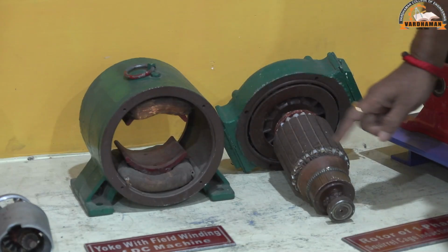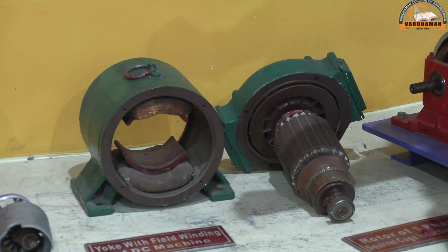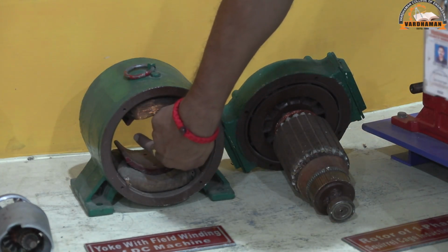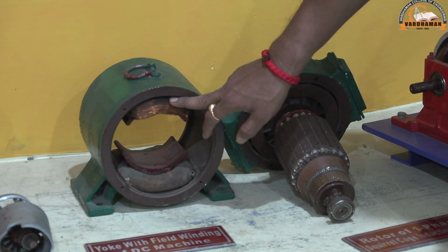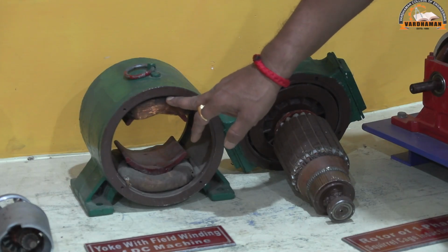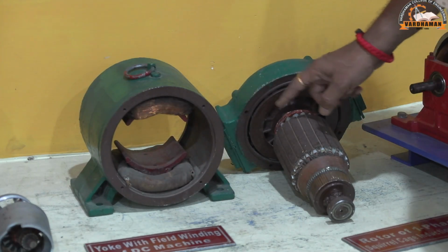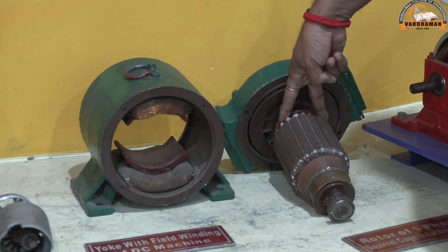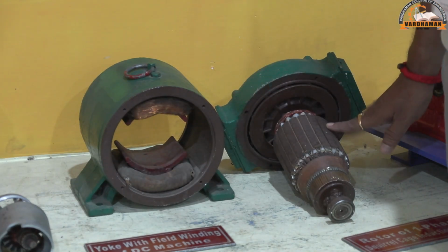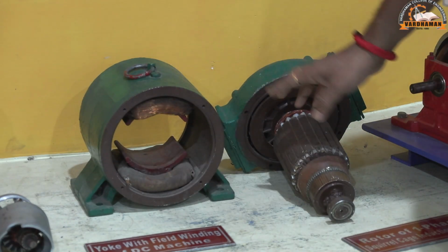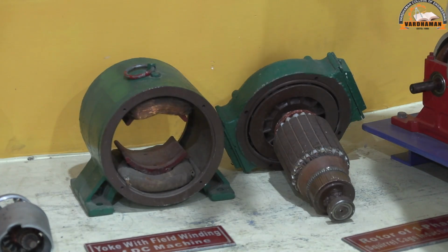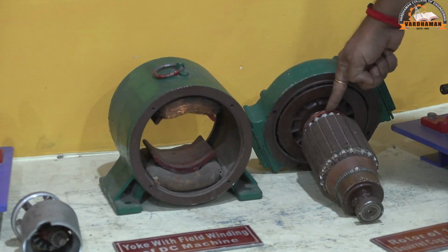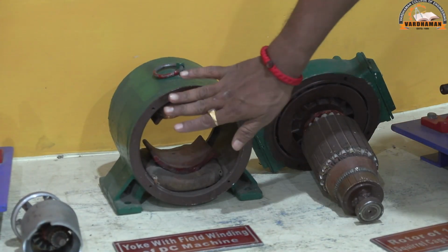it works on Faraday's laws of electromagnetic induction, which state that whenever a current carrying conductor is placed in the magnetic field, there are two types of magnetic fluxes. One flux is produced by the electromagnetic field coil. The other flux is produced by the current carrying conductor, which is given a DC supply as input. So there are two types of fluxes interacting with each other and exerting a force. That force is mathematically represented as F = BIL sin theta. That force perpendicularly acts on the conductor and pushes the conductor to move. Thus the rotation starts in the motor.